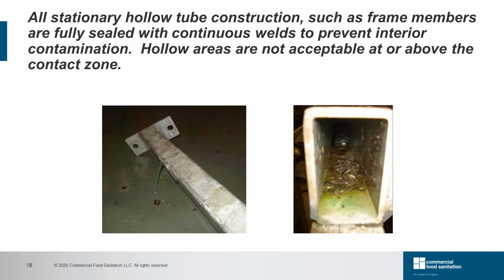All stationary hollow tube construction, such as frame members, are fully sealed with continuous welds to prevent interior contamination. Hollow areas are not acceptable at or above the contact zone. Hollow support structures represent contamination risk in food production areas.